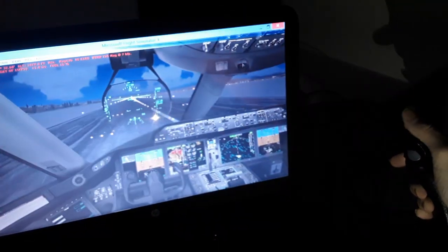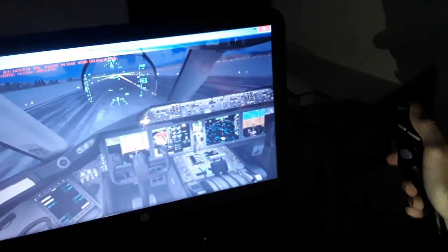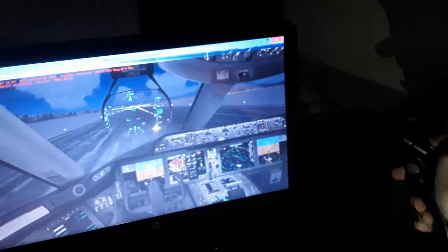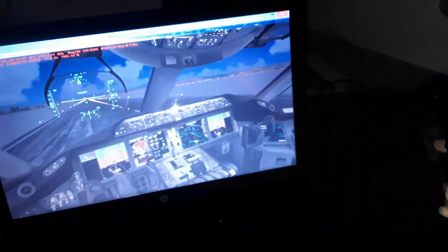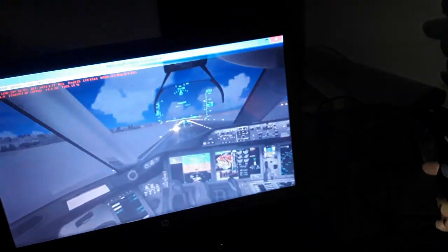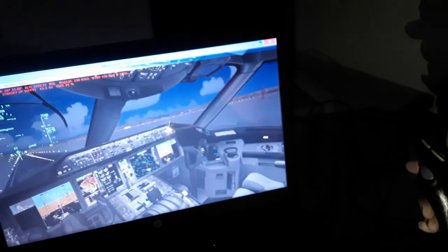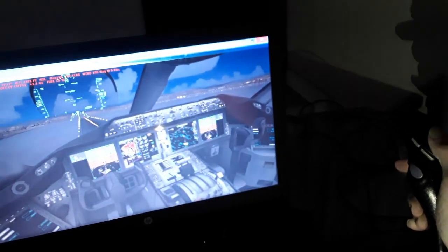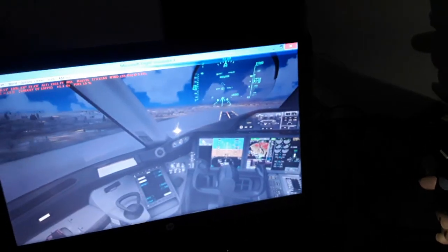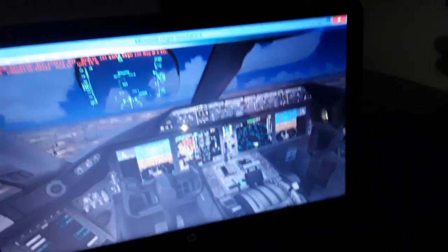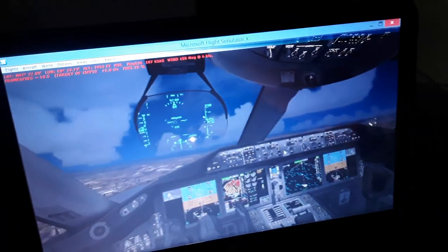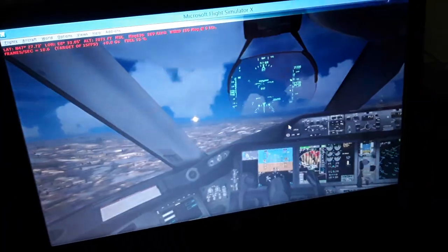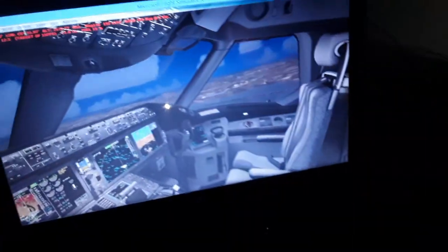So we align now with the runway center line using a little bit of rudder pedal. So we have 130 V1. We rotate 9 degrees, pitch 9 degrees like this, smoothly for rotation for takeoff, so we won't strike the tail on the runway. We need to pitch the aircraft only 9 degrees or less. Other aircraft have slightly different limits. So we climb.